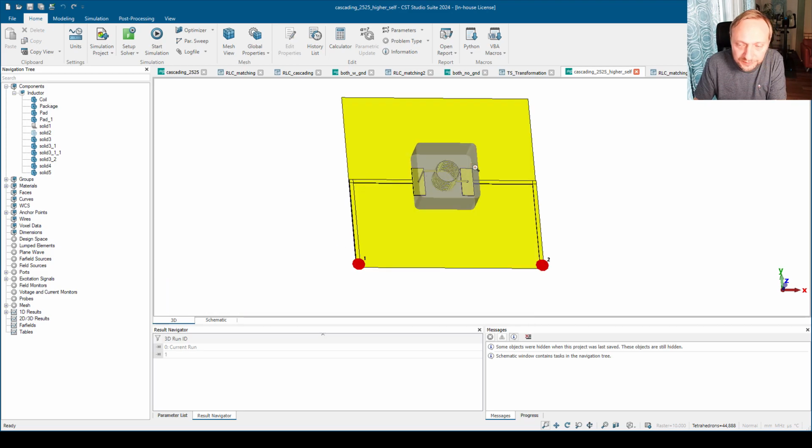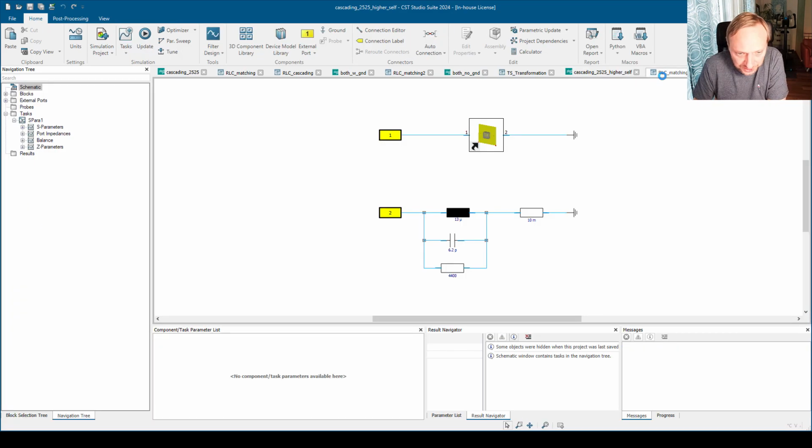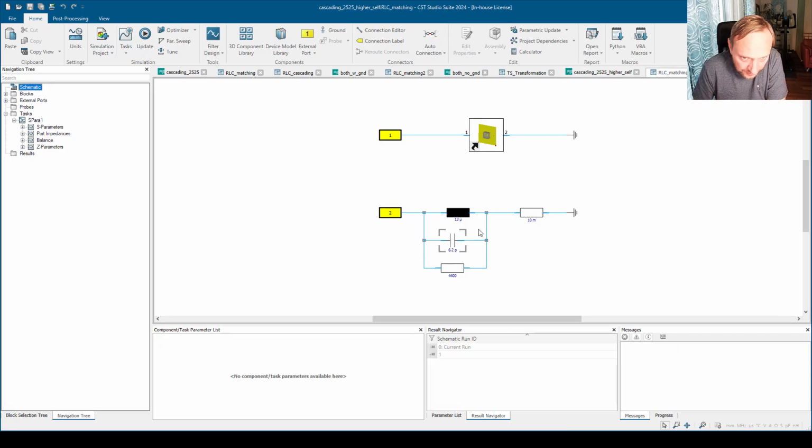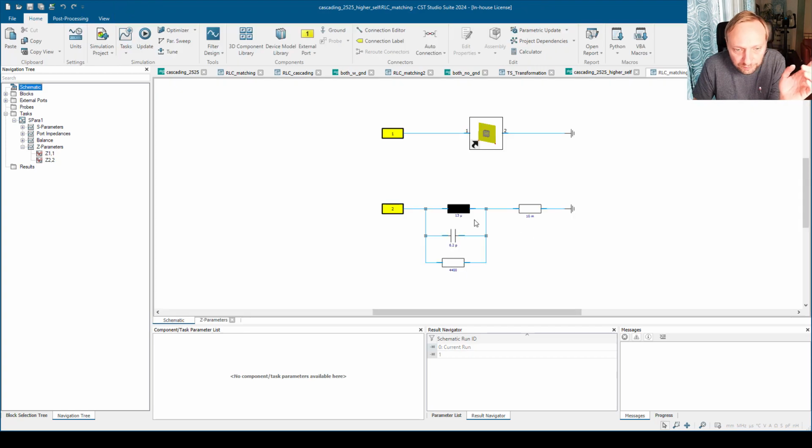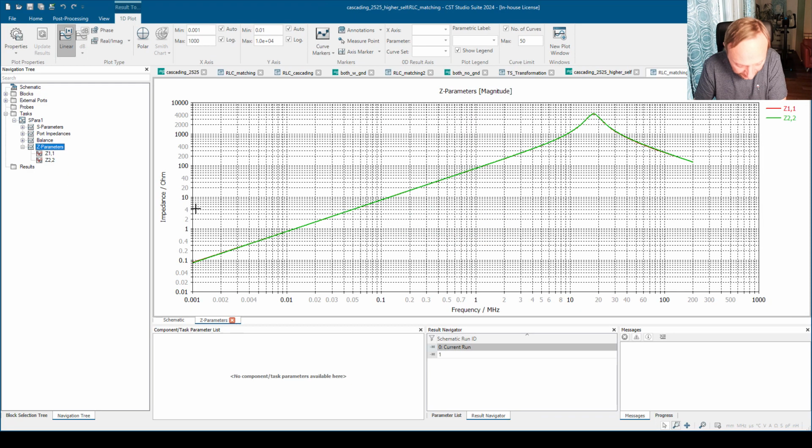That's what I'm doing. And now if we start matching, you see now this self-capacitance, so I have the calculation of the standalone inductor, and if I define a circuit like this, again, I can make these Z parameters match each other in a standalone inductor by using 6.2 picofarad. Previously it was 3.6. So you see, I have to increase this parallel capacitance to make this match.